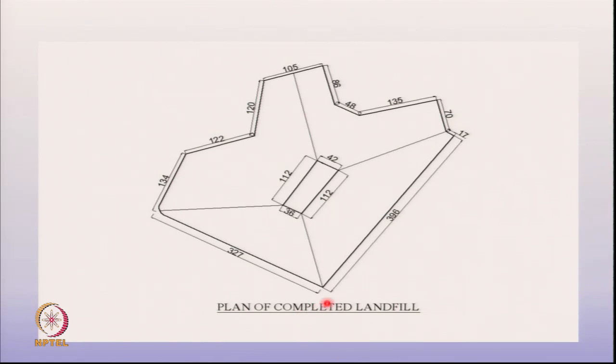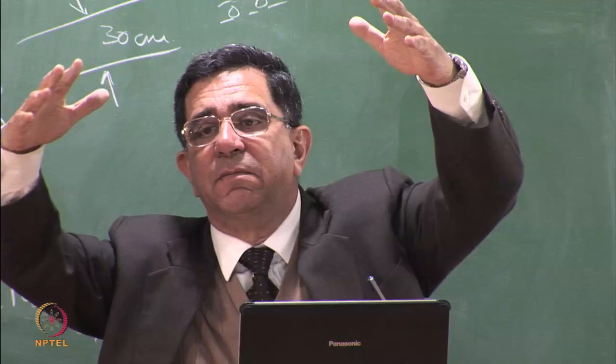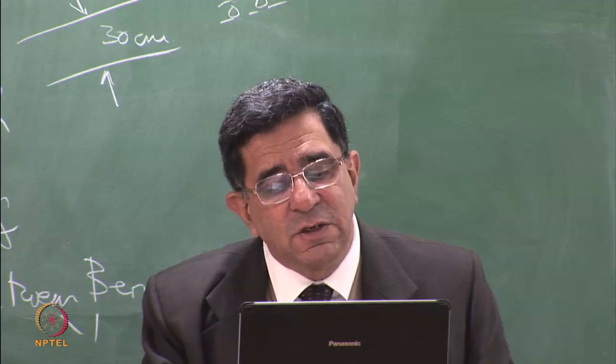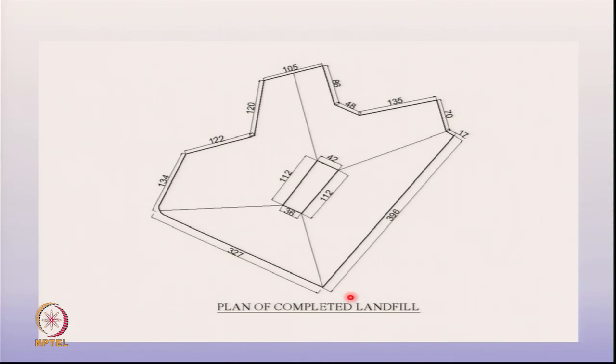This is what the landfill looked like in plan. And this is the top of the landfill and the base profile, and this is the little flat ground at the top. It's like a conical mound going up, okay? And do see that this is about 300 meters, and if you are coming 4:1, 30 meters, 120 meters will go here, 4:1, another 100, 200 meters will go there, all that will be left at the top is 40, 50 meters.